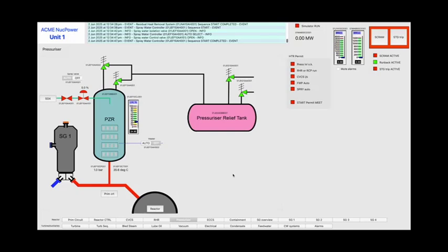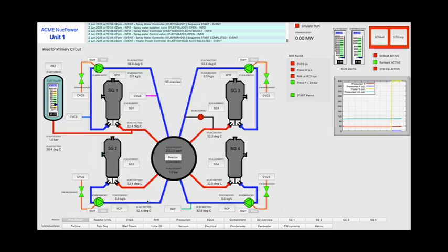Welcome back. The reactor plant is now ready to commence warm-up of the primary circuit. All the permissives have been met and we can start the electric heater elements. Note that all heater elements start initially but will later turn off or on to control the temperature at set point. Primary coolant temperature has started to rise.